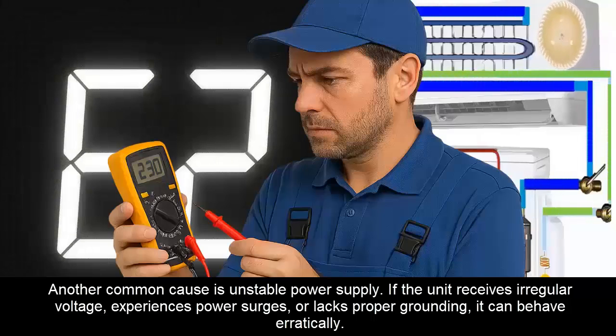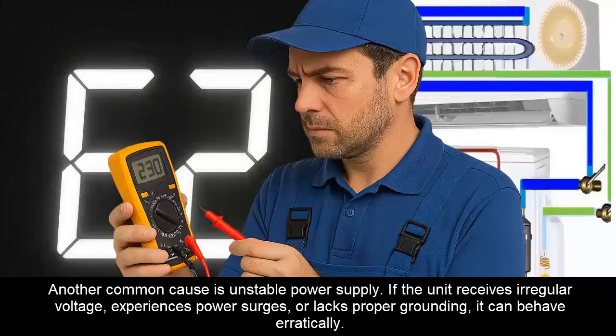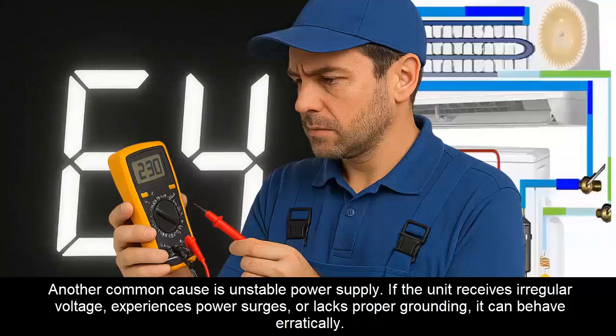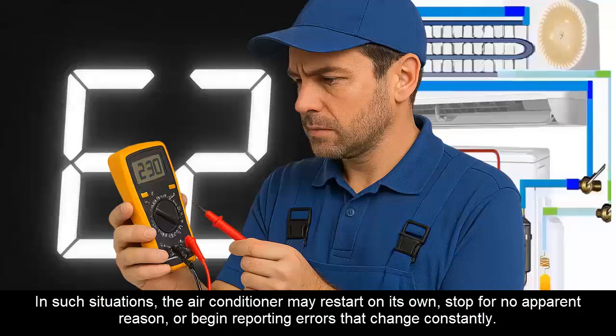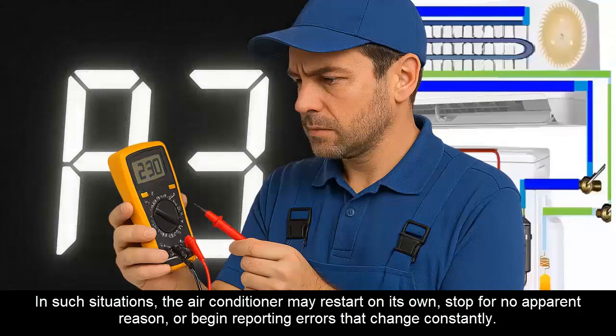Another common cause is unstable power supply. If the unit receives irregular voltage, experiences power surges, or lacks proper grounding, it can behave erratically. In such situations, the air conditioner may restart on its own, stop for no apparent reason, or begin reporting errors that change constantly.